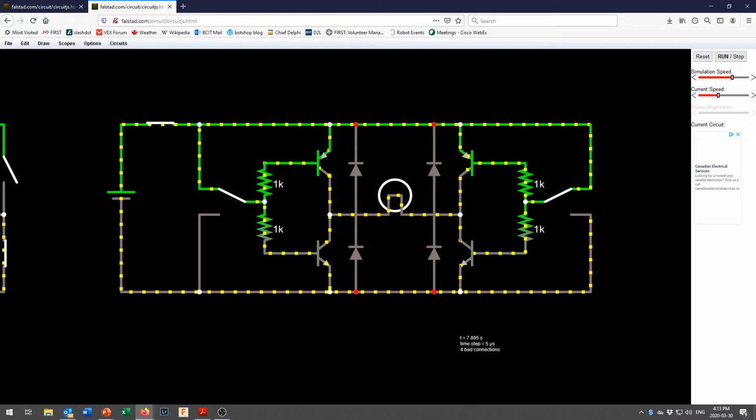You can think of it as kind of being like a vacuum effect, the vortex left behind. You felt that when a semi-trailer truck goes past you or something like that. There's that big sucking vortex where the air pressure behind the truck is actually lower than ambient. It's just temporary and it's localized, but that's what can happen right here. And this allows electricity to flow in, fill up that big sucking voltage vortex, and prevent damage to your chips. So if you hear someone talk about protection diodes in a circuit, these protection diodes are actually quite important to making your circuit work reliably.